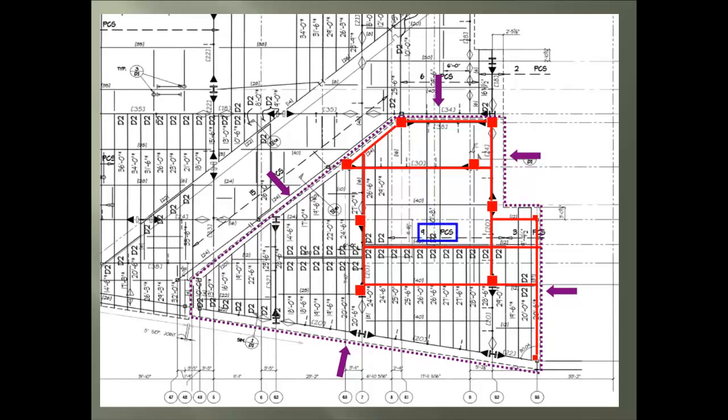But we see the call out for 9 pieces of decking in this bundle. Okay, no problem. We just reviewed this. And they start here and finish there. Okay, that should make sense. But wait, we have this call out, which means you have 3 more pieces within this separate bundle that connects to the bundle we just saw and runs to the edge of the deck.